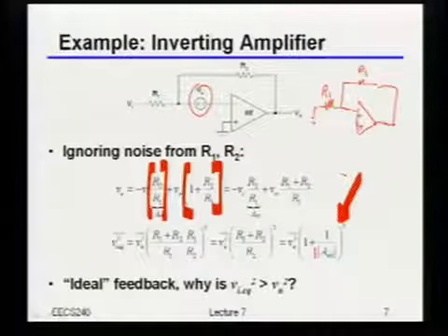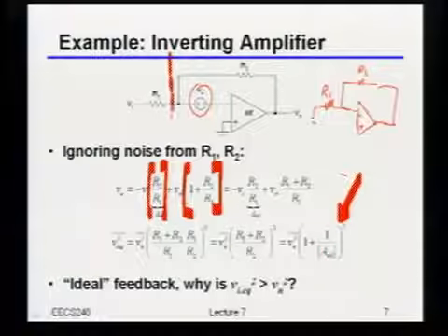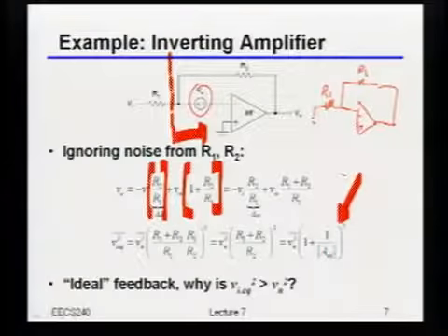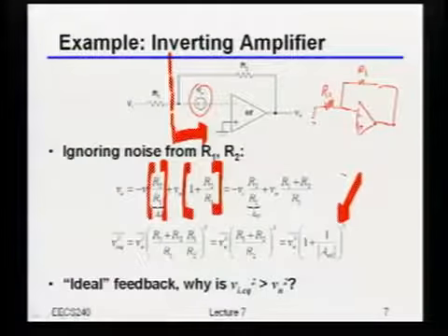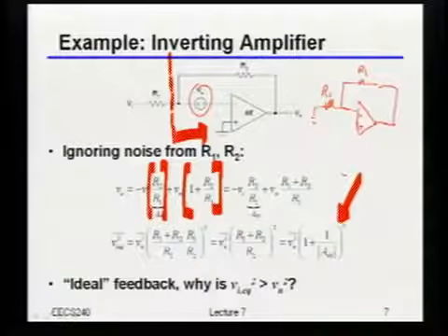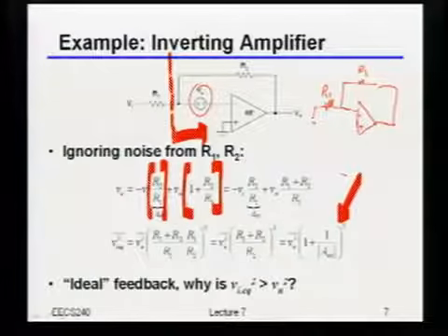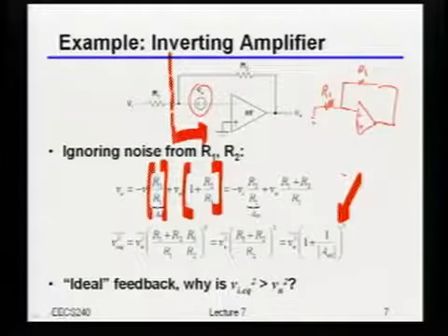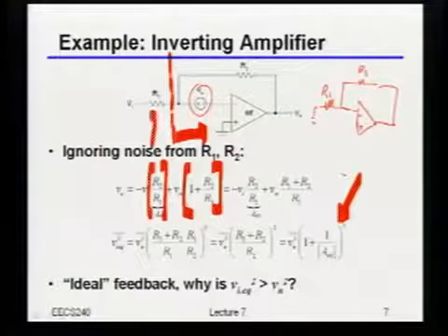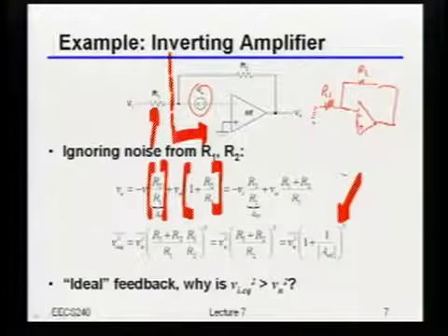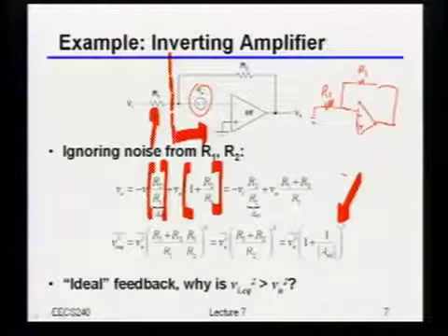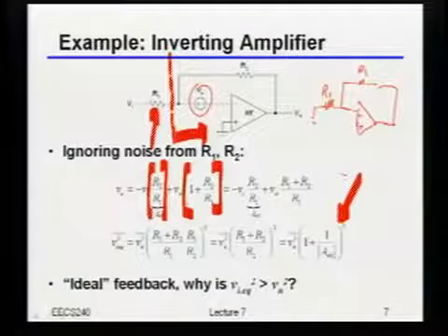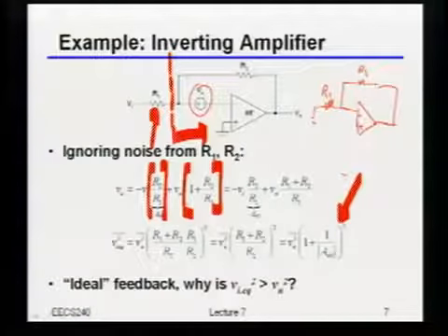What is that related to? I'll give you a little bit of a hint. What does that thing on the right over there look like? Source resistor. RS. There we go. Okay, so that thing on the right, that's the shunt feedback amplifier, right? That shunt feedback amplifier has some input-referred noise current, effectively, right? So now if I add this other resistor in the front right here, what I'm basically doing is changing the source impedance, right? Well, as soon as I change the source impedance, bingo, I'm going to get a different noise at the output.